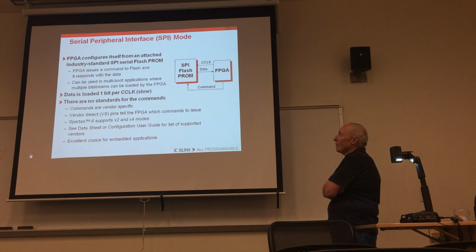Note that the available SPI flash PROMs use a single 3.3 volt supply voltage. All of the FPGA SPI flash interface signals are within specific I/O banks. Consequently, the supply voltage for the I/O bank must also be 3.3 volts to match the SPI flash PROM. This implies that any I/O pins assigned by the user into the I/O bank must also be 3.3 volt compatible.